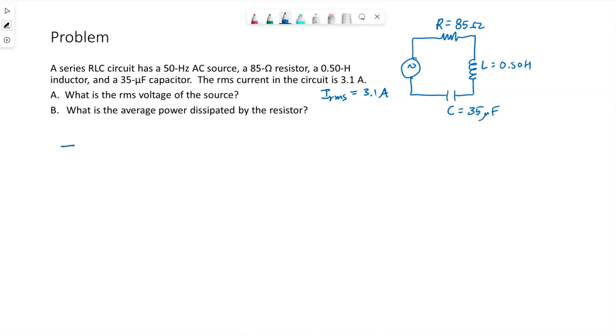So in an RLC circuit, in series specifically, the current in this series circuit is the source voltage over Z. Now it's written in terms of max values, but we've seen in previous videos, if we divide both sides by the square root of 2, this max over square root of 2 is the RMS value of the current in the circuit, and then the maximum source voltage over the square root of 2 is the RMS voltage.